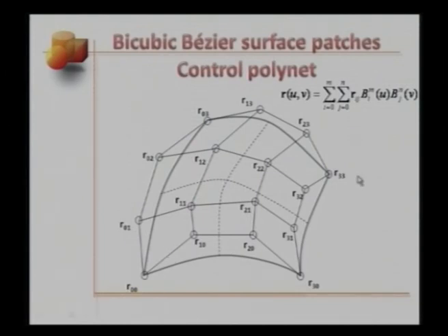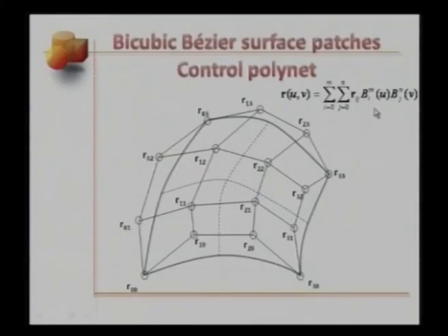As you know, Bernstein polynomials are barycentric, but that's not a local property, as we have seen in case of B-spline basis functions. Rather, if we use B-spline basis functions over here in place of Bernstein polynomials, and we'll be studying these models later, the corresponding shape changes will be local.